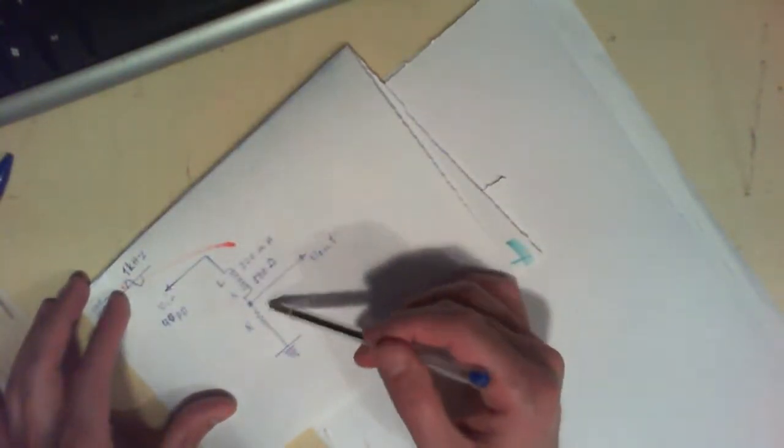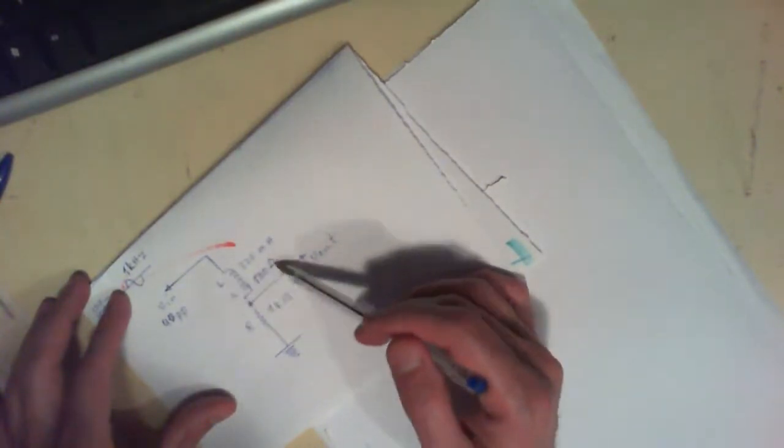Okay, so we want to first go through the DC output of this circuit. So if DC comes in, you have this inductor over here and this resistor, and this becomes a simple voltage divider circuit, and there would be a 500 ohm resistor here, a 1 kilo ohm resistor here.